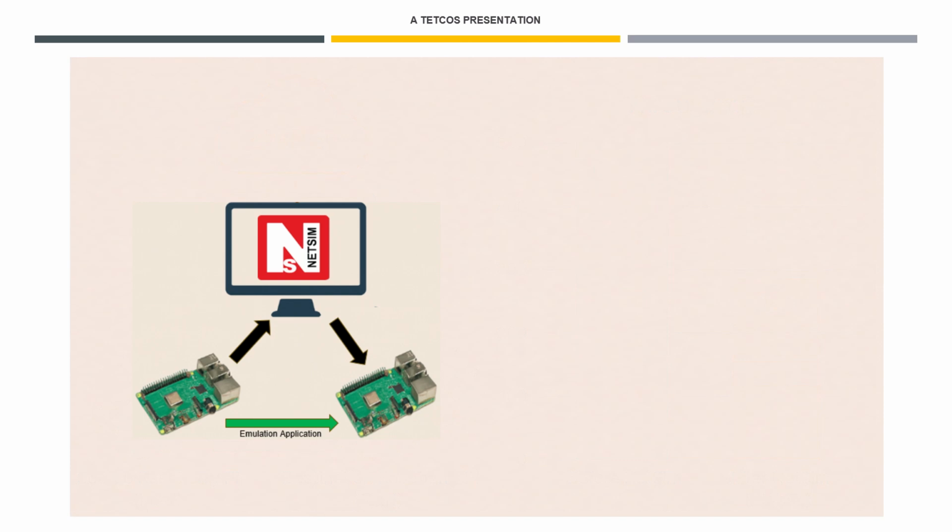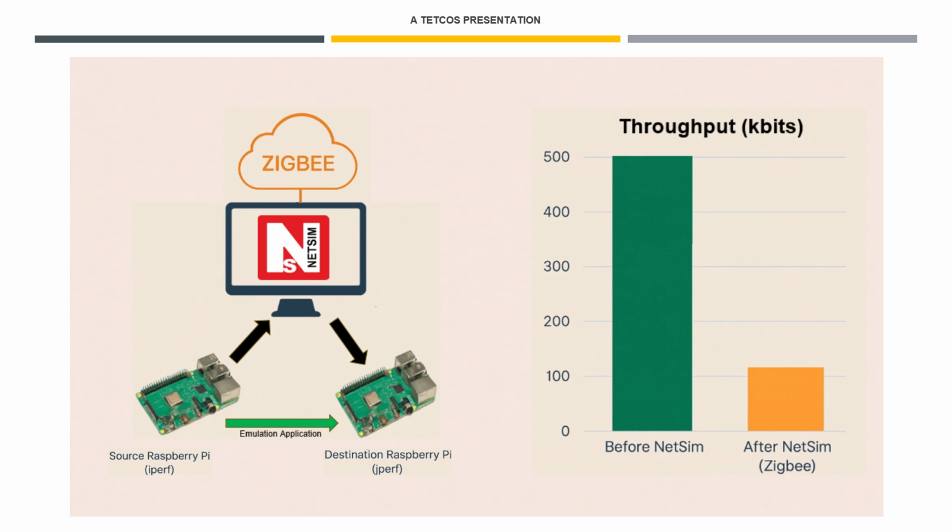To summarize, we connected two Raspberry Pis to NetSim in emulation mode. Real iperf traffic from the source passed through NetSim's Zigbee network before reaching the destination. The throughput dropped as expected, confirming Zigbee's performance characteristics. This demonstrates how NetSim emulation can bridge real devices with virtual networks, creating a powerful hybrid IoT testbed for research and learning.